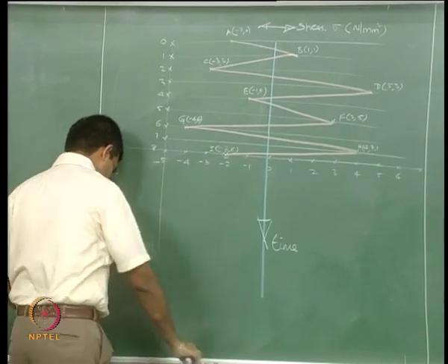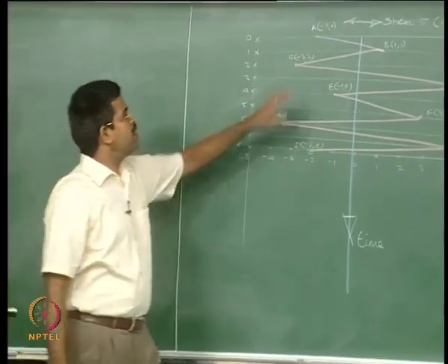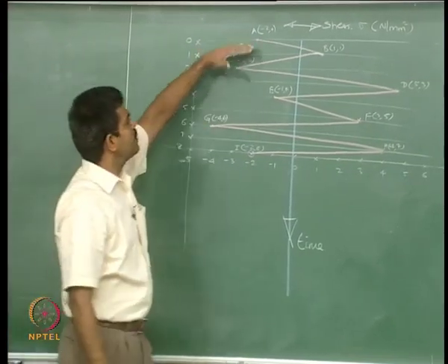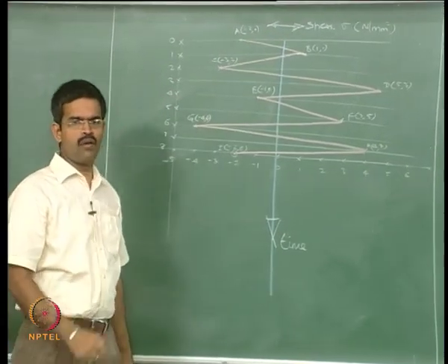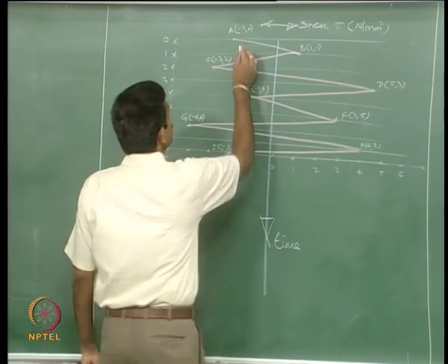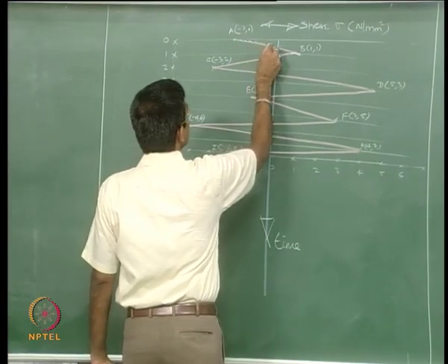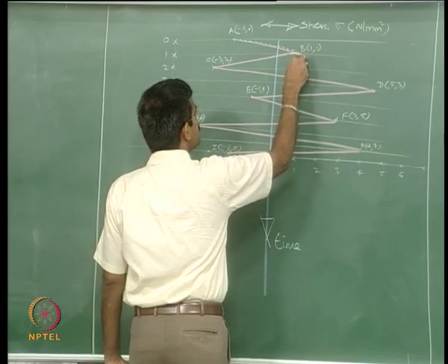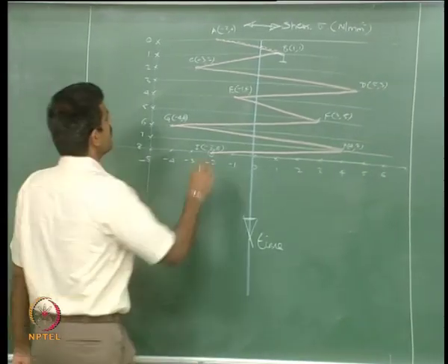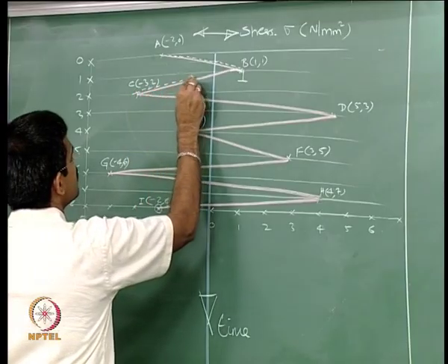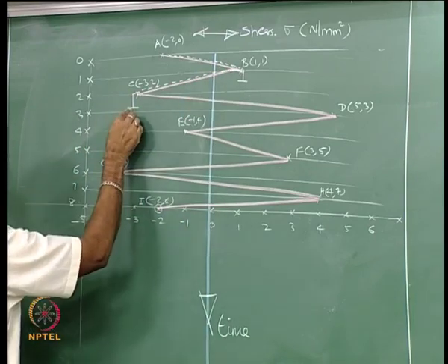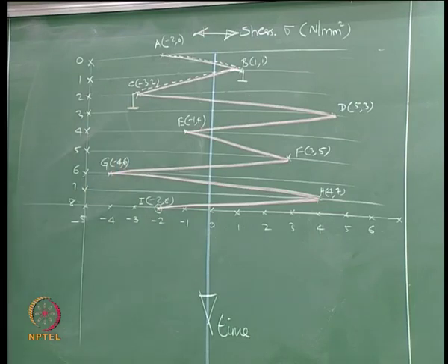Now what I do is start from a valley and allow a raindrop to fall, simply a raindrop falling on the roof. What will happen is the raindrop will roll over the roof and keep on rolling until there is a roof projection available. Let us try to draw this in dotted lines. It comes here and it stops. Similarly, the other one starts from here and stops. These are terminal points.